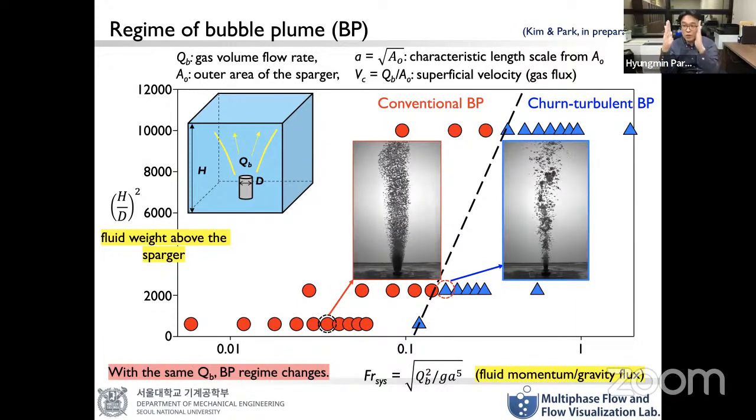But what happens if you narrow your tank size to be comparable to the size of the bubble plume? Then with a turbulent bubble plume, we didn't check yet, but the turbulent one will be more effective or should be comparable between the two, because in that configuration the lateral oscillation will also play a very significant role in enhancing mixing, as you can imagine.